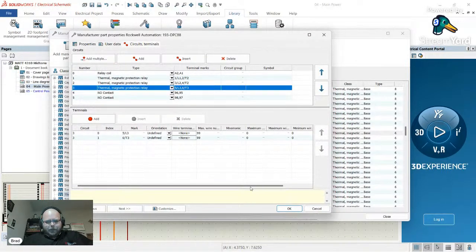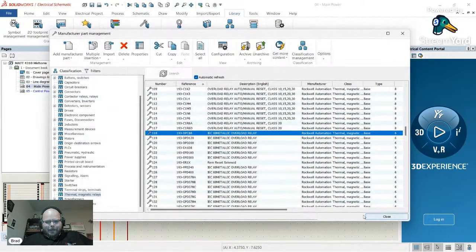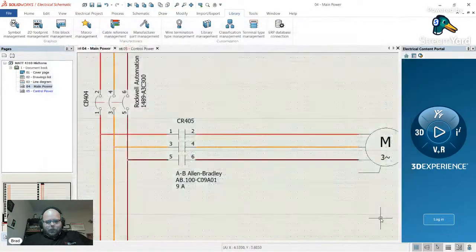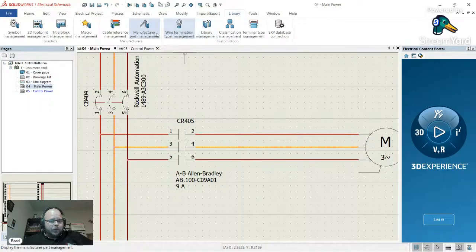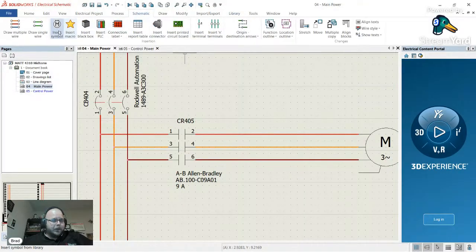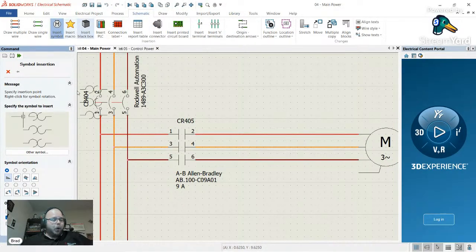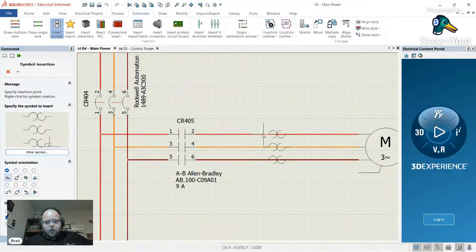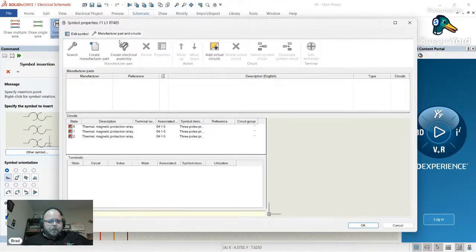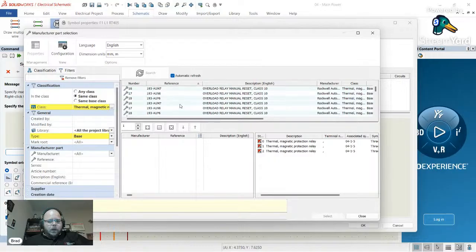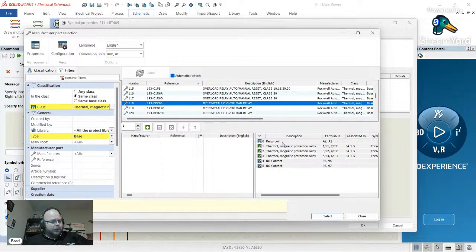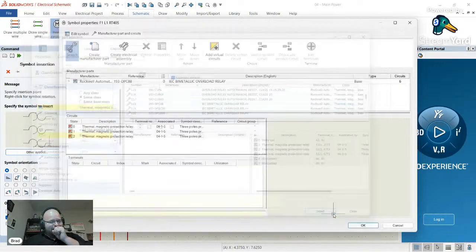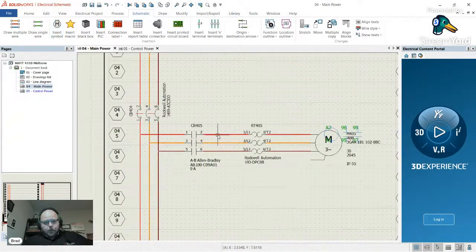The thing to be very careful of when you're doing this is to make sure you don't have existing sheet sets using the other version, the original downloaded version, because if you go to change those someday, that change is now permanent in my entire installation of SolidWorks. So if I go to change an existing drawing that used the original, and I update it, it's going to change that drawing, and that's one of those changes that I may never see. So we throw the protection in there.